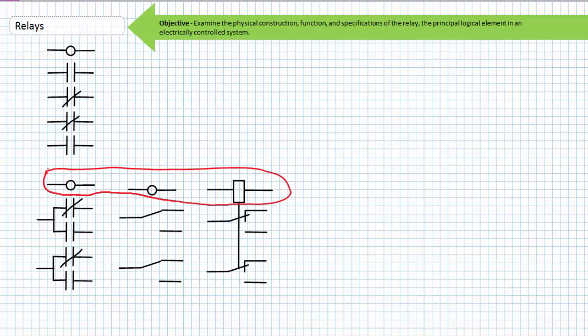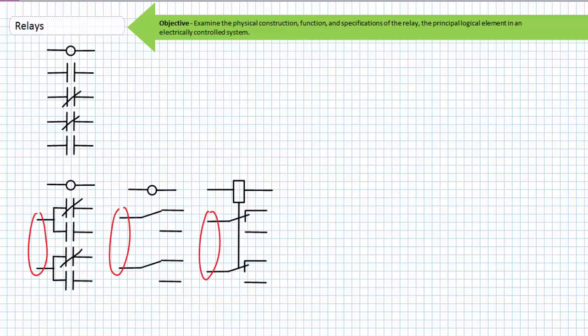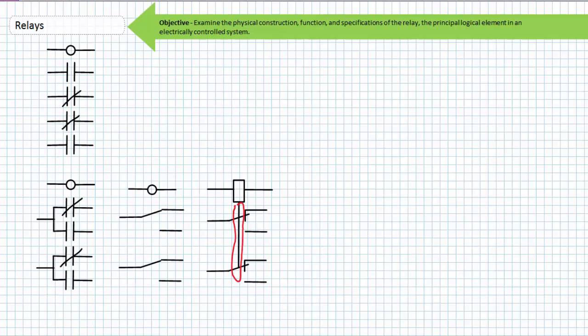This is the coil. This is the common side for two single-pole double-throw switches. This is the normally closed side. This is the normally open side. The IEC schematic symbol makes it very clear the switches are controlled by the mechanical interlock with the coil. In either case, the switches are isolated from each other, and the switches are isolated from the coil.